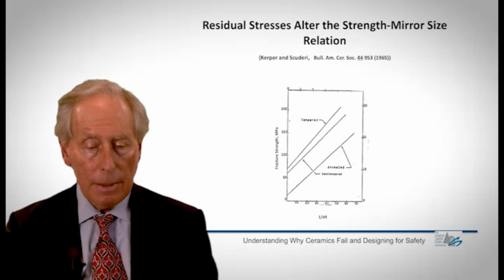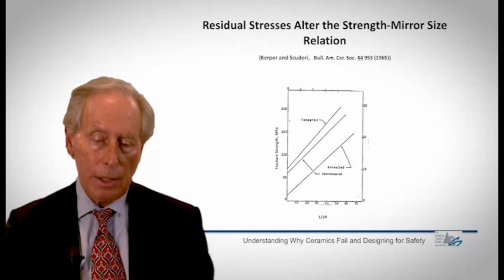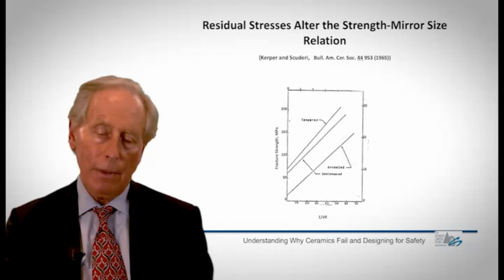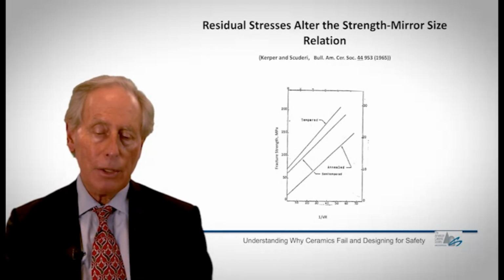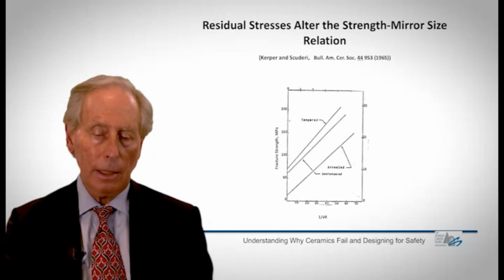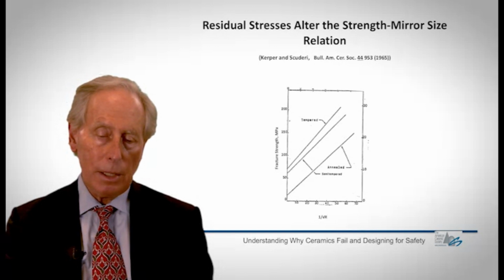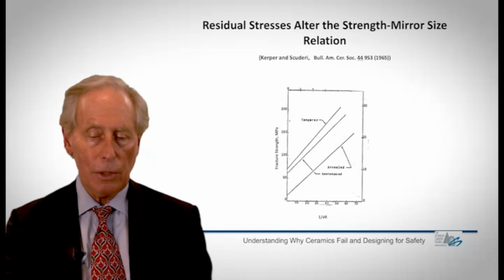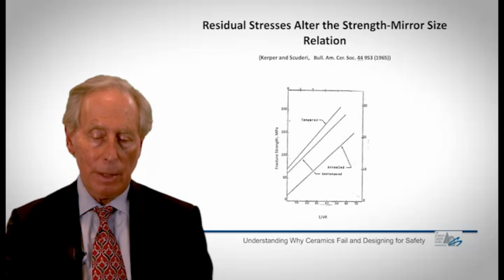So you can see that completely annealed glasses pass through the origin. If I have some degree of macroscopic residual stress in the glass because I didn't anneal it, what is called tempered here, then the curve is displaced by some amount, and that's equal to the amount of residual stress left in the glass. So that again is a useful piece of information.